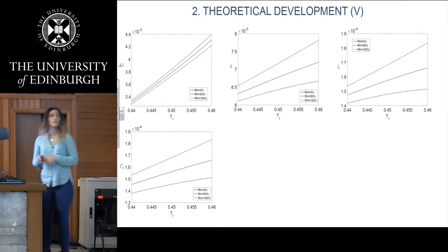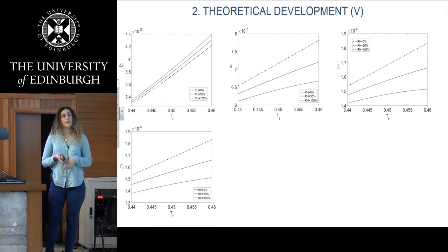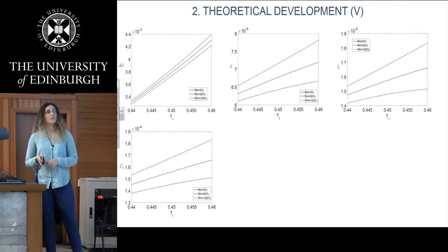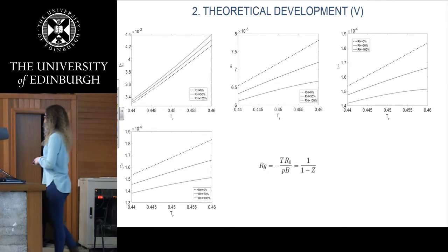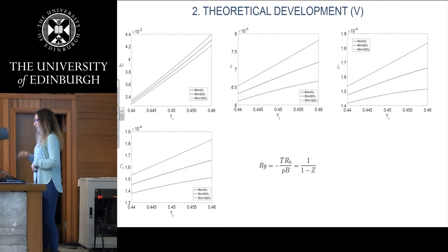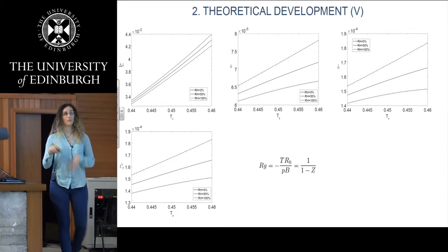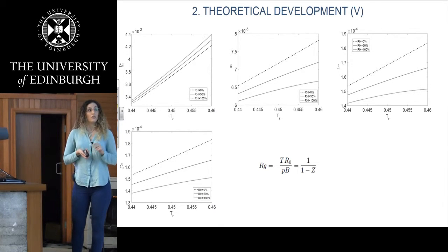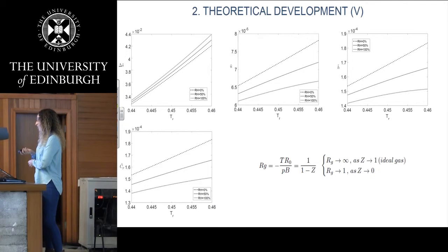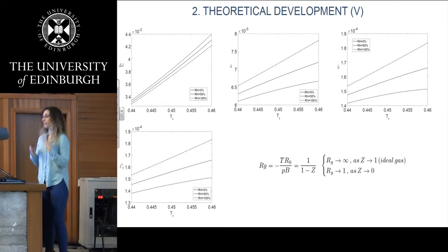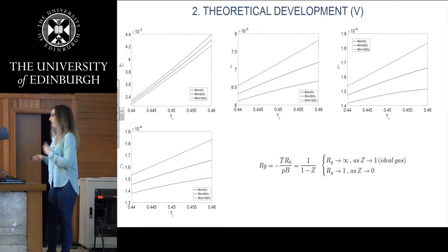And in terms of energy, internal energy U and enthalpy H, both are different forms of energy, and you can see that the real gas is less energetic than the ideal one. When I was doing the non-dimensionalization, I found that this term, T R P V, was always repeated. So I decided to call this the real gas non-dimensional number. And these are the limits of this number. So I think it's quite useful to compare different gases, how real they are.